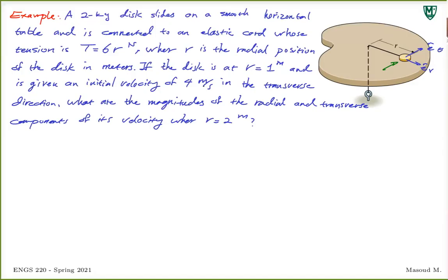Pretty much this is also a central force motion because T is always towards the center. If you think about your coordinate frame somewhere here, ER and E theta attached to this cord, you're going to have a central force motion again. But we are going to use both the principle of angular impulse and momentum and the principle of linear impulse and momentum to solve this. I will see what the story is.